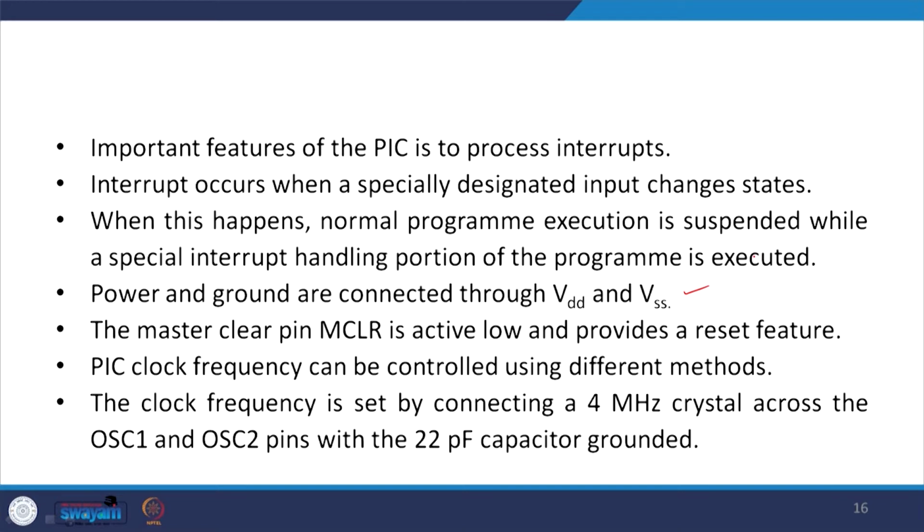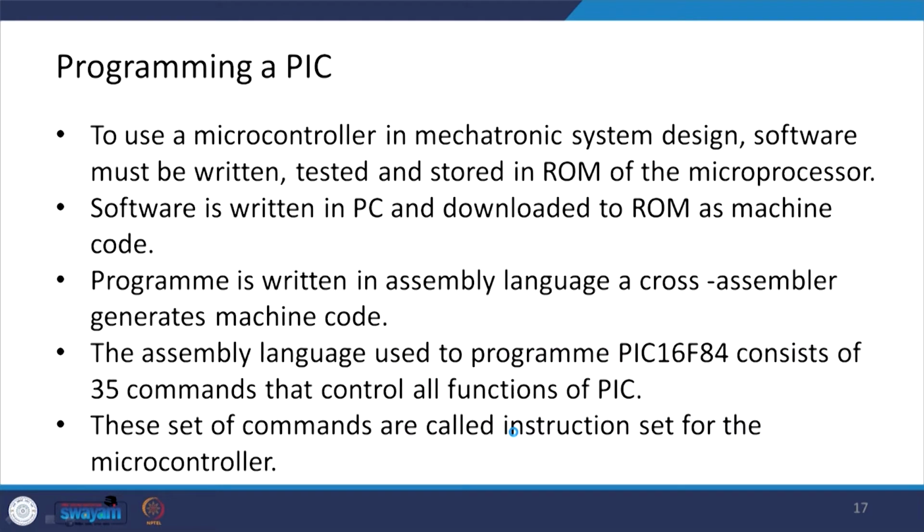As I said, the master clear pin MCLR is active low and provides a reset feature here, and PIC clock frequency can be controlled using different methods. The clock frequency is set by connecting a 4 megahertz crystal across the OSC1 and OSC2 pins with a 22 picofarad capacitor grounded.